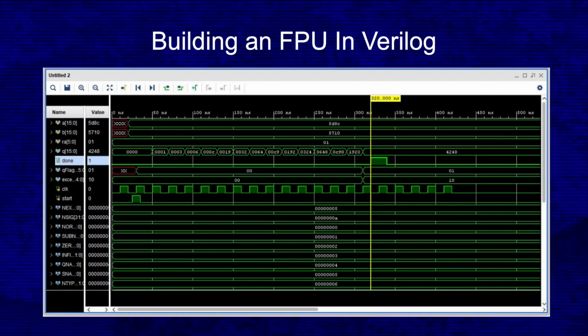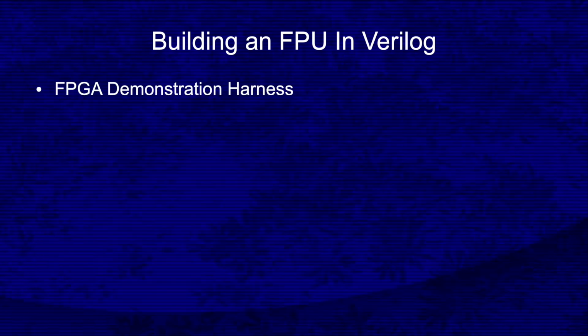One other thing to note about the done signal. It's asserted and deasserted on the falling edge of the clock. That way the signal meets any necessary setup and hold times to be successfully monitored on the rising edge of the system clock by other components in the system. Now that you've seen the simulations, it's time to show the circuit in operation.